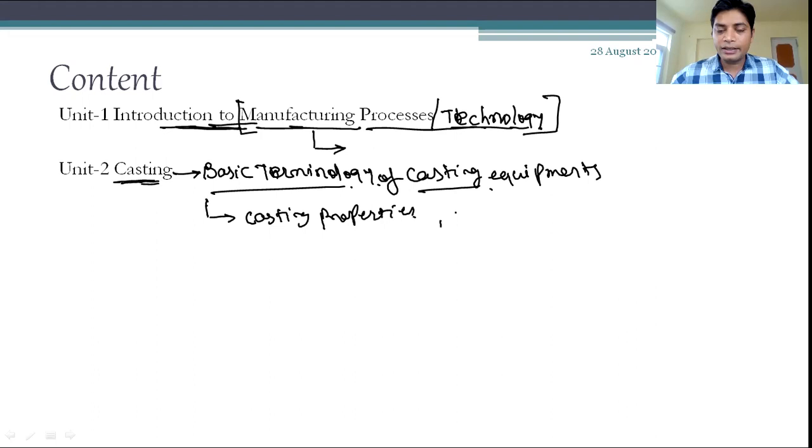Apart from that, whenever we fill molten material into a specific container or mold, how will the material come out? If there is a container in which you have filled the molten material, and once it solidifies you take it out, you can turn it upside down and put a hammer on the opposite side. Another way is to put the hammer on the side wall and turn it over, then the material will come out.